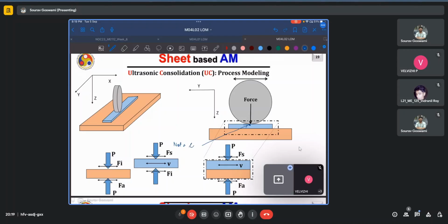You would expect that if I have this cylinder on top of say this flat plate, the contact will only be along a line where the cylinder is coming in contact with the surface. However, we know that because of the action of the normal forces, some Hertzian contact stresses will develop at the surface, and this contact will actually be not a line but an area contact.